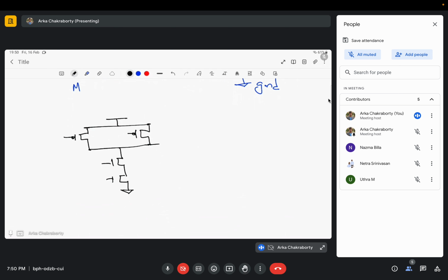Say for example here, if I take the Elmore delay model, it would be 2, 2, 2, 2. So here it would come 2c because of this one, and here it would come 2c plus 4c, that is 6c. You do this, this and this, it will come 6c.